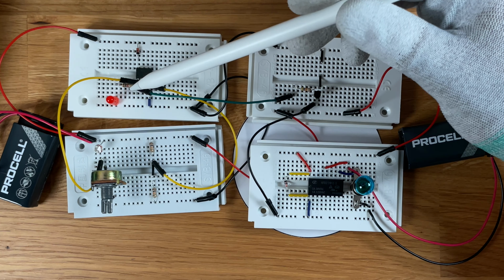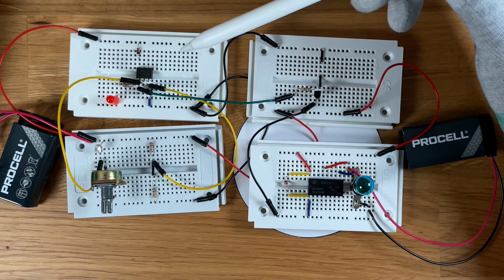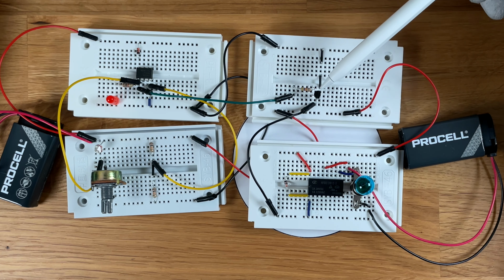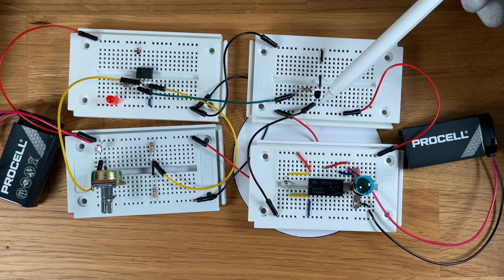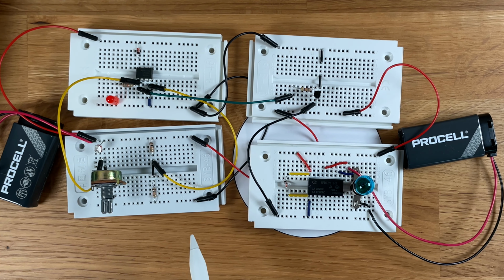As soon as there is an output voltage, which is generated by the LDR, the current running into the base of the transistor connects the collector to the emitter. We have a current flowing, and this current, alongside a voltage drop of course, is driving this relay circuit. I'm going to make a video on this relay circuit in a few days, but the idea of it is to trigger a second circuit.